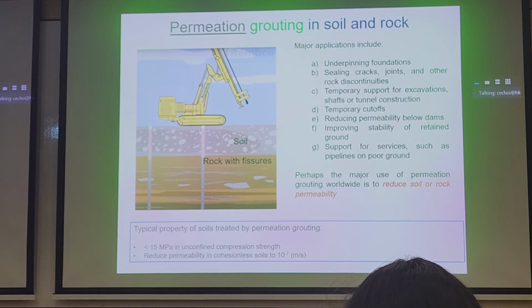I received a question from a student today, I think this is one of their interview questions. Name one problem related to post land reclamation in Hong Kong. The answer must be residual settlement, right? Like secondary consolidation creep. We still have to calculate that after ground settlement.